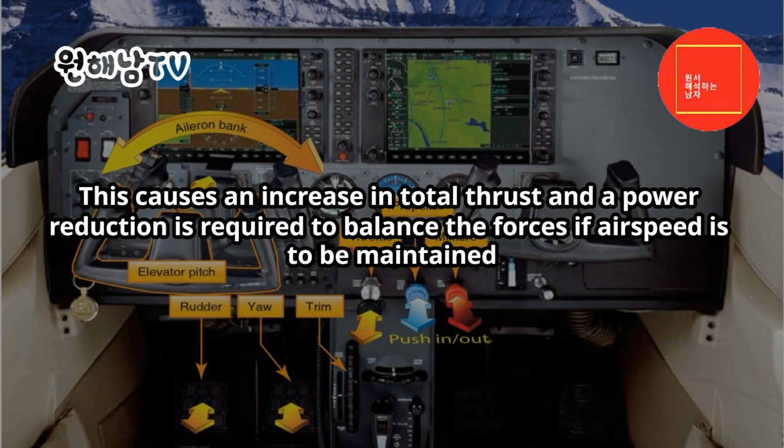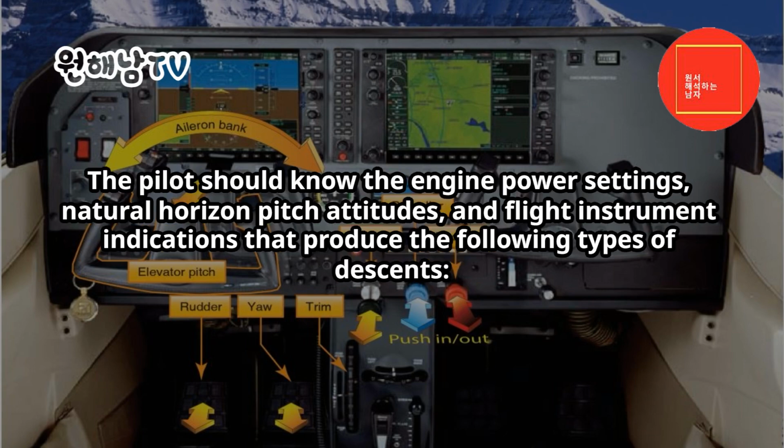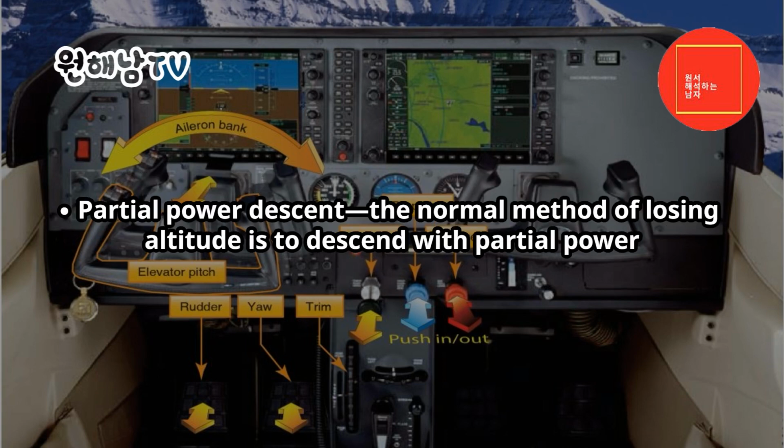The weight-gravity force is about the same. This causes an increase in total thrust, and a power reduction is required to balance the forces. If airspeed is to be maintained, the pilot should know the engine power settings, natural horizon pitch attitudes, and flight instrument indications that produce the following types of descents. Partial power descent.